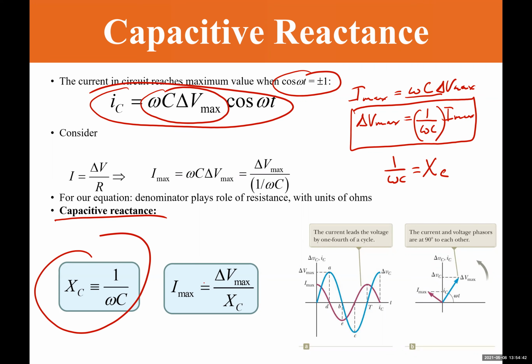Then I can rewrite the equation for the current as the voltage, which is a driving mechanism, and the reactance is the opposition mechanism. That means the voltage divided by the resistance or reactance in the circuit. Okay. And again, one thing we can see here is this reactance is frequency dependent. So if I'm looking at x sub c as a function of omega, what is x sub c when omega is 0? When omega is 0, you get 1 over 0, which is basically infinitely high.